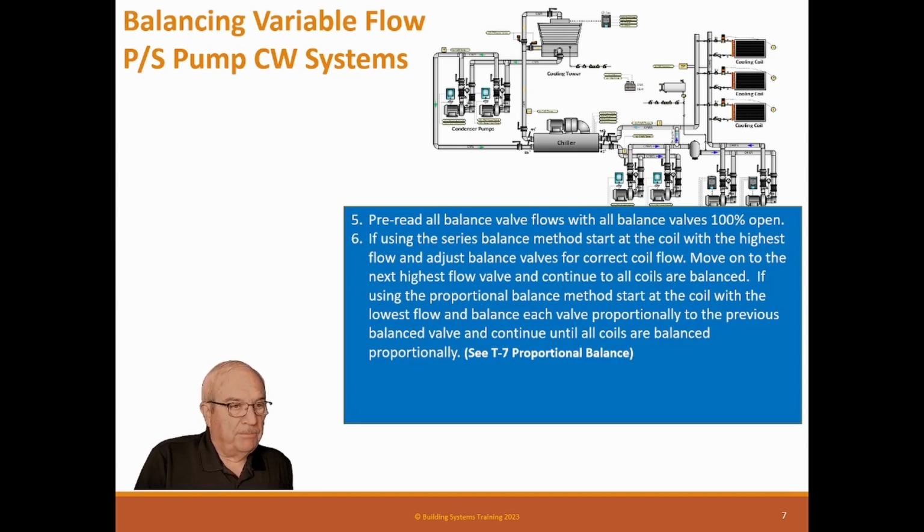Well, the beauty of the proportional balance is you don't ever have to go back. You know what I mean? As you work your way around, if you don't get to the water you want, you may have to go to a couple of the bigger valves and get them down a little bit more to push a little bit more water to that valve. But proportional actually gets to be easier if you have a whole lot of valves.